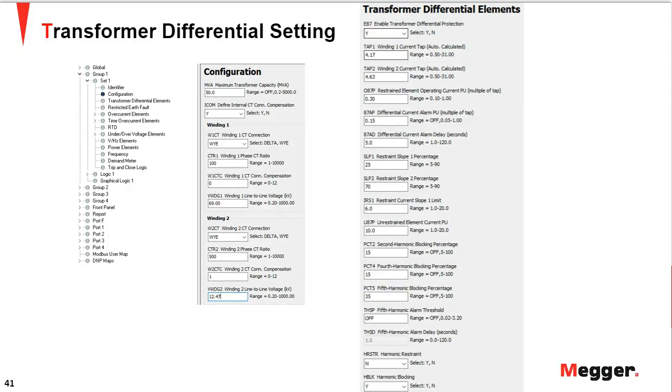Yeah, so I believe the question is related to the sensor technology that a lot of relays these days have. For currents, they usually have either a Rogowski coil sensor or a low power current transformer sensor for detecting the millivolt signal, basically replacing the CTs. Rogowski CTs are used to avoid CT saturation problems that can happen in traditional CTs, but the output of those Rogowski sensors is in millivolts. So I believe the question is towards that direction.